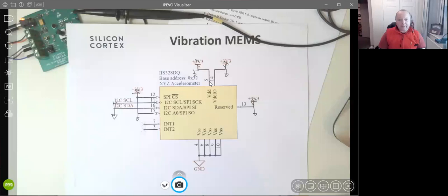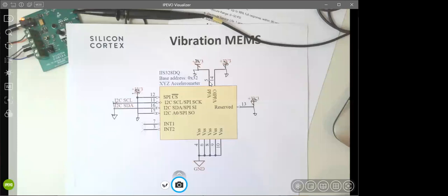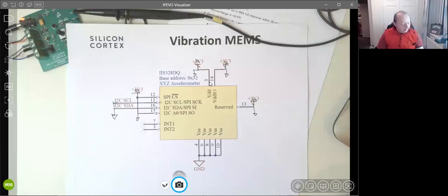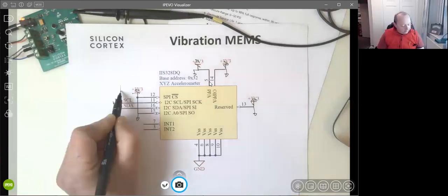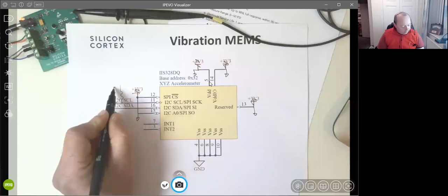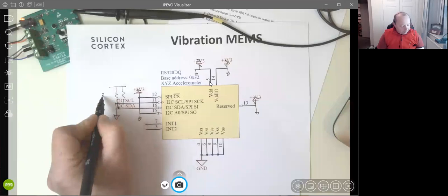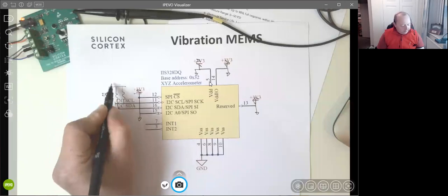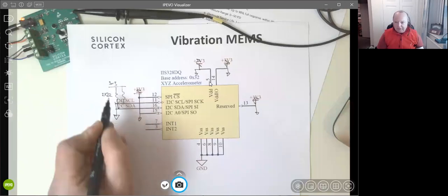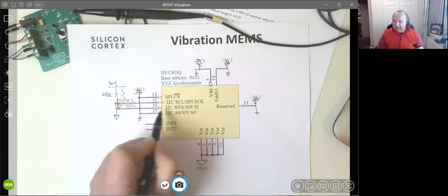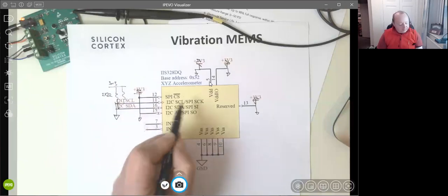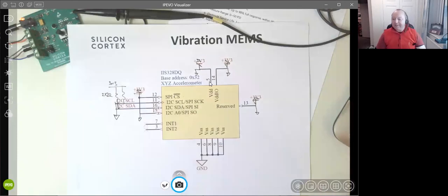In other words, don't ever do what you just talked about happening, because you may well damage the device. Yeah. Even though the I2C was through a couple of pull-up resistors, perhaps 2K7, there's still sufficient current to keep the thing alive. So there's a word to the wise.